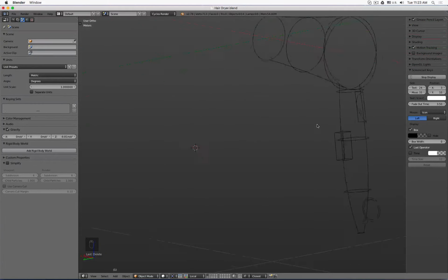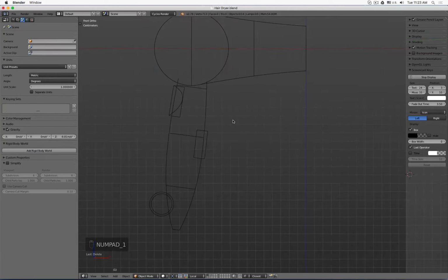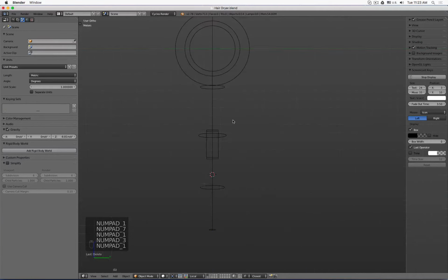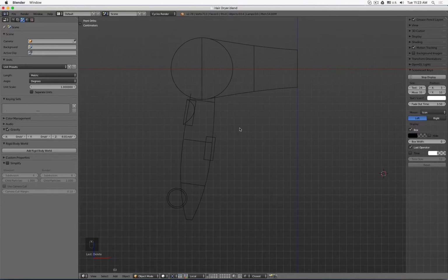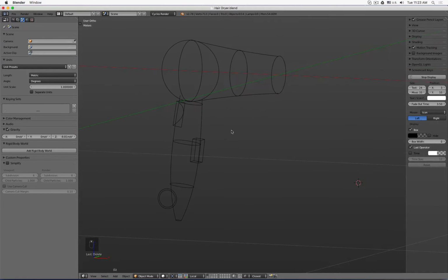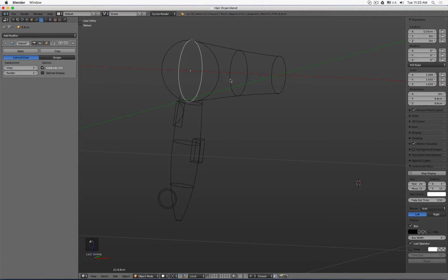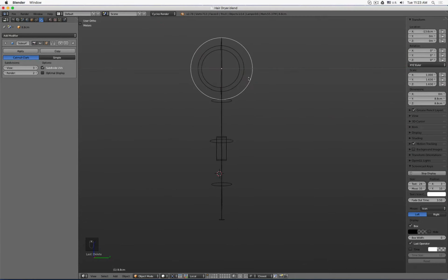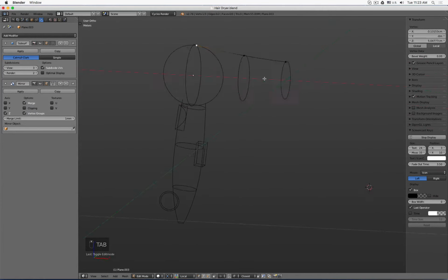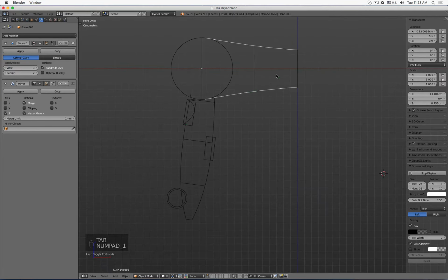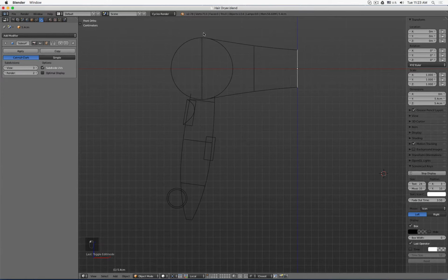And this basically is an advanced version of just having profile images, which are just 2D. In our case, we simply create three-dimensional sketches, which, as you can see here, describe, for example, the radius, and if I see it from the front, and maybe here there's the other radius or the back, and then there's, for example, some additional lines to create a reference, for example, how from here to there maybe the surface could be lofted or webbed.